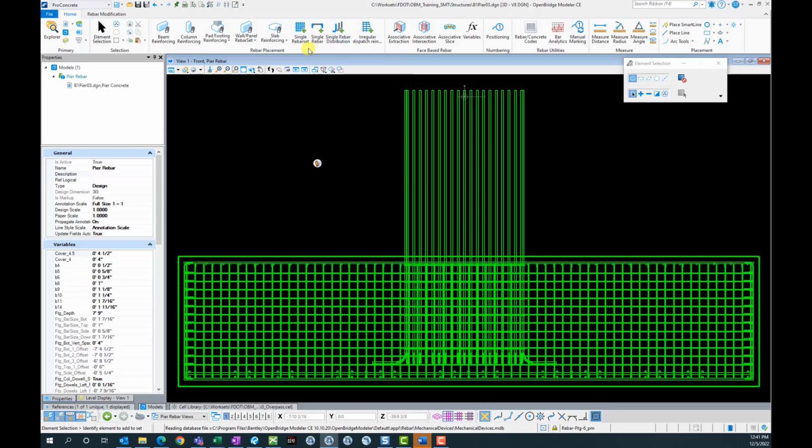Now, the custom reinforcing tools use guidelines to position the bars in 3D. And those guidelines can be manually drawn. That's workflow A. Or workflow B would be, they can be driven from the faces of the concrete. So you can do face-based rebar guidelines. You can extract the concrete faces to produce the 2D guidelines that the custom reinforcement tools use. And that's typically the recommended workflow. Because that way, if the concrete ever changes, if this footing got taller or longer or wider, then those extracted faces move along with it, and your rebar automatically updates and moves along with the concrete as well.